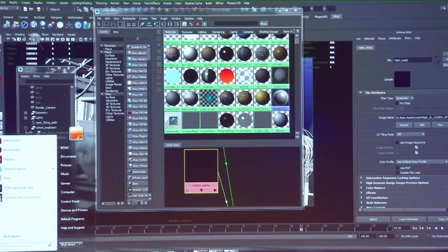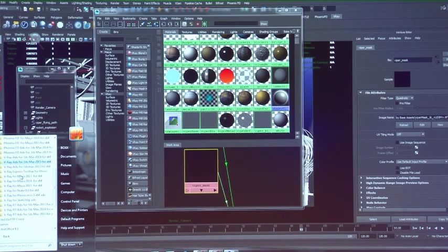And we provide a tool for you to convert any of your images. Since only TIFF and EXRs can be tiled, you have to convert them into tiled images. So we do provide a tool for that. If you go into the Chaos Group folder, depending on your installation, you will have a tools folder under V-Ray for Maya, for example, here.